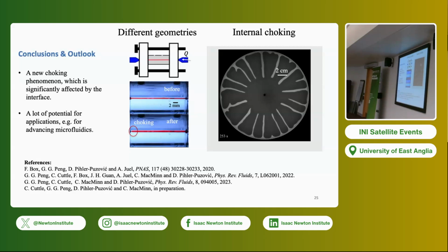Did you try experiments that impose pressure instead of imposing flow rate? Yeah, it's a very good question, and the two are not interchangeable. We've tried it, and it still works, and I suspect that adhesion actually helps in that scenario. But if you were to just do the modeling that we've done, it turns out that there is always a steady solution if you control pressure instead of the flux. However, what happens is that the bulging gets extremely close to the opposite wall. And at that length scale, probably other physics takes over, right?